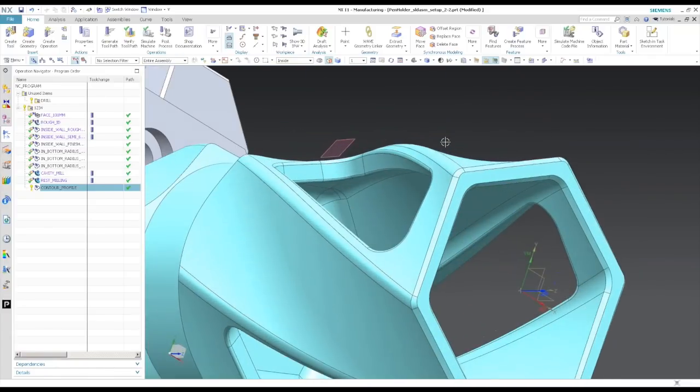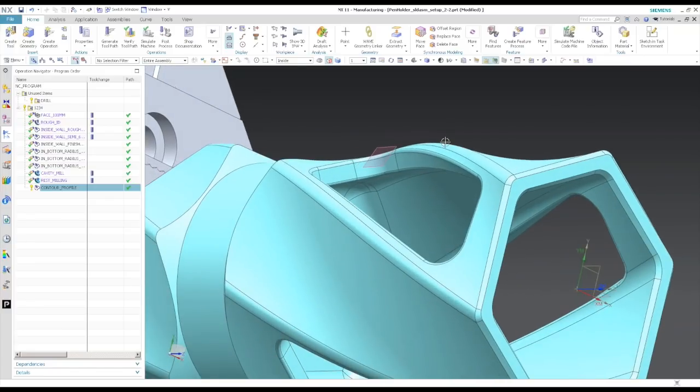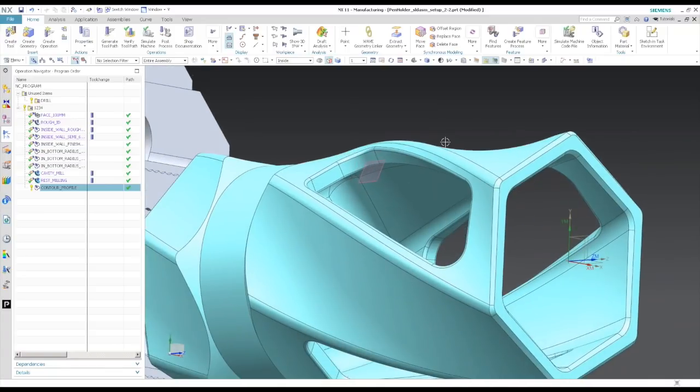As you can see here, there's quite a bit of twist on these faces, which doesn't make something like away from line or towards or away from point type of tool axis work very well. So when you encounter faces like this, you certainly need to be able to look at the U and V lines. And if you're not aware, CAM systems look at either edges or UV lines as one solution for multi-axis swarf cutting.